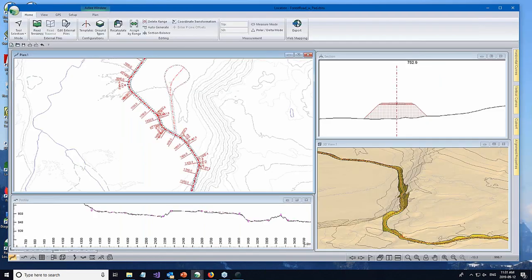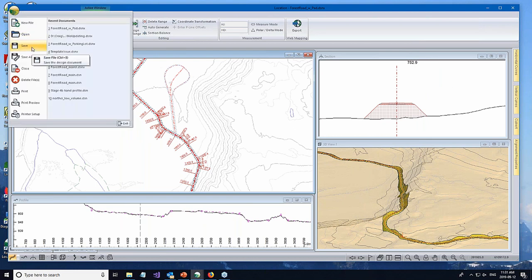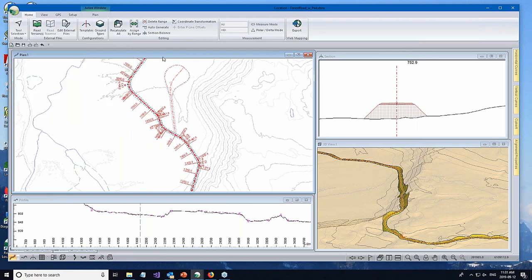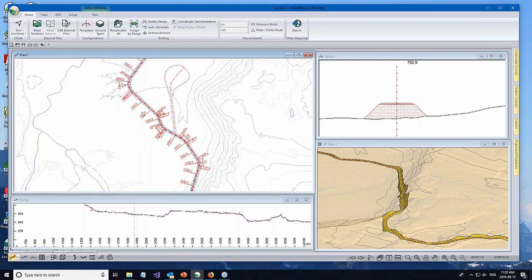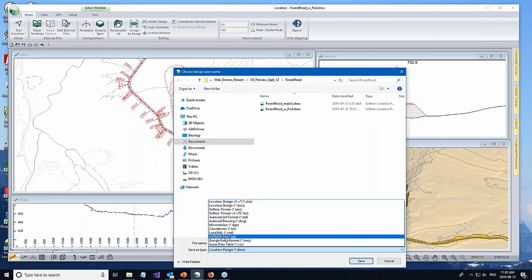Very similarly now, when you go to slope stake this, and if you've got some instrument that takes a LandXML file, total station, or even machine grading applications, you want to save your design out as a LandXML file, and you want to save it as a LandXML surface.